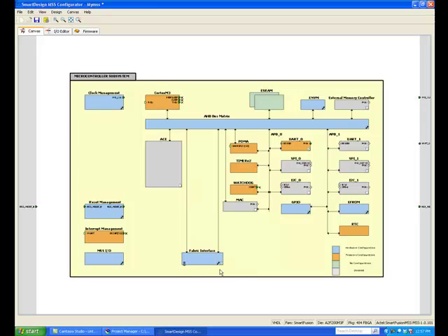To connect the MSS master APB port to the fabric, you must right-click it and select Promote to Top Level. We are now finished configuring the MSS for this design example. Click the MSS Generate button to complete the MSS design and turn it into an HDL component.